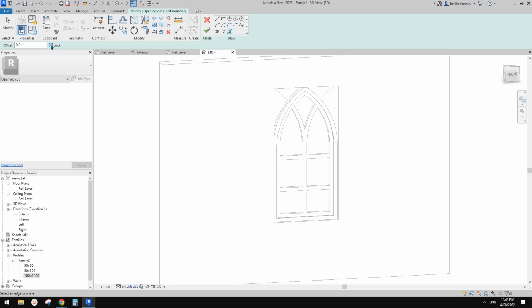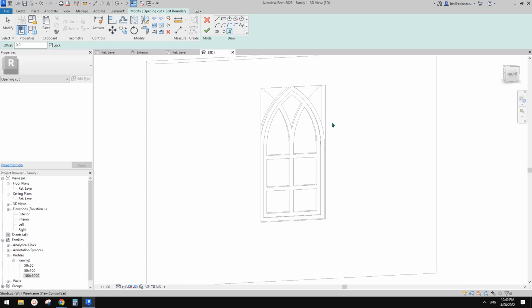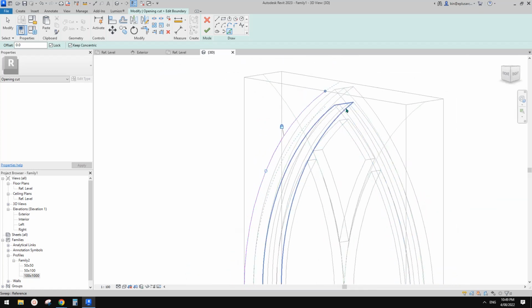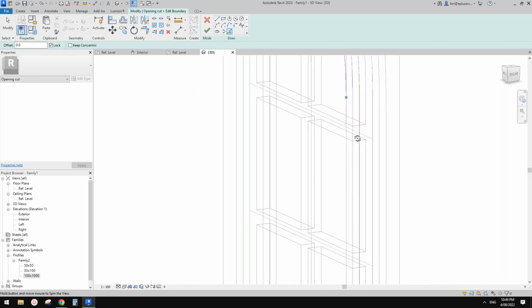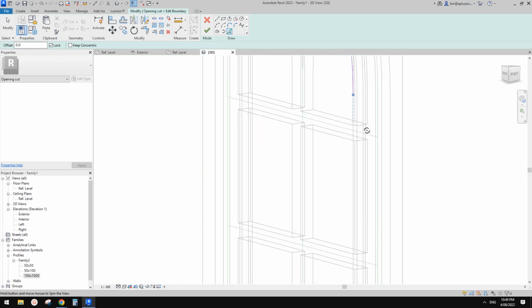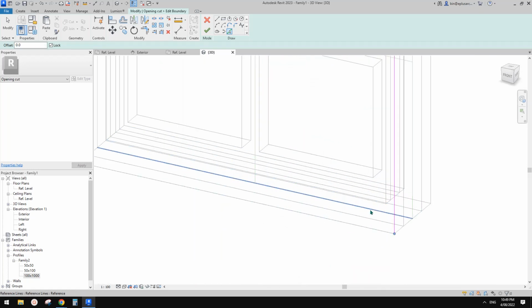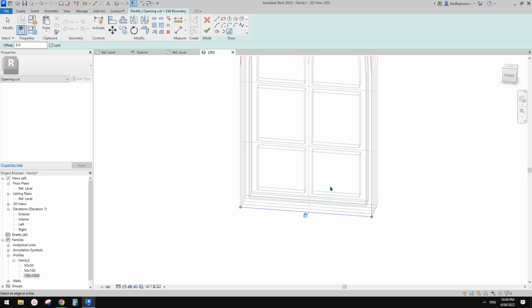Okay, so we're going to delete these and then pick those reference lines. So I'm going to just check this box and type WF, so it's easier for us to find those reference lines. This one, where is it? Here. So the blue lines, they are reference lines.